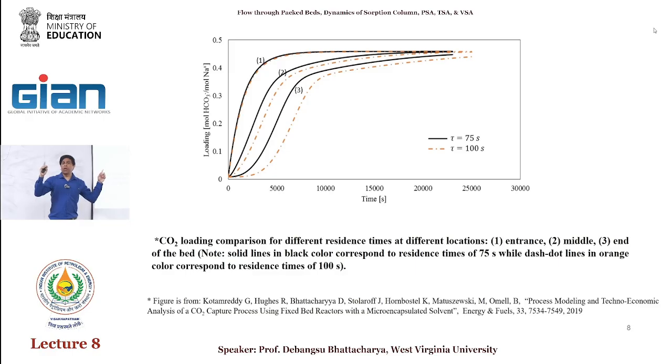If any of you are from natural gas sweetening processes, there are hot caustic wash processes people have used for sulfur removal. Potassium hydroxide and sodium hydroxide have been used there. You have to heat them up to quite a high temperature to make those solvents flow. Otherwise, they are very viscous. So if you have a viscous solvent, this is the way to utilize it.